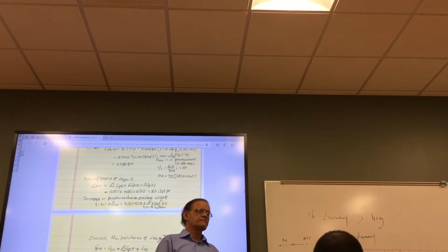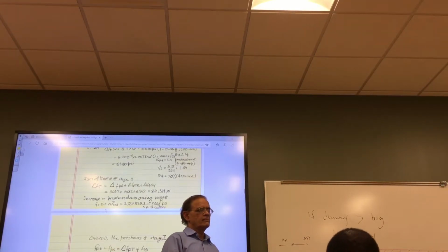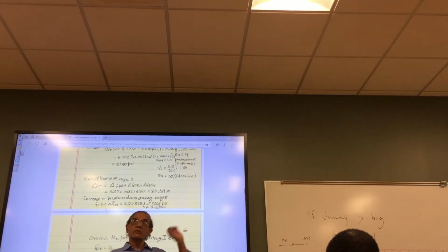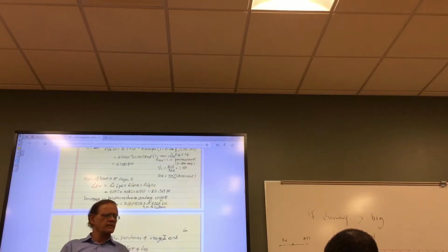But now when we add the topping on top of the element, it is not because of adding that we have lost. Before we added this topping at 30 days, we have already lost pre-stress to relaxation and friction, depending on what we are doing. All those things have creep.